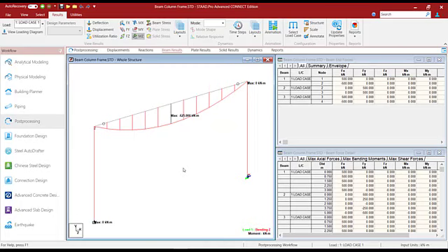Now, if you think about what we had achieved from the structural analysis from the real field condition, the beam moment should have come out to be 380 kilonewton meters. Now, this is a 64% increase in the beam bending moment, which would lead to an overestimation of the beam material if we are to use this particular simulation.